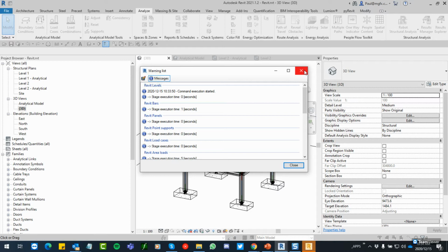So typically the sort of error that you might find, you perhaps know if your minimum CPU RAM is able to handle these programs simultaneously. No, I don't. I don't know what the minimum is, but minimum, that's a relative answer to me. If I can answer it differently, Marcus, just from a Revit modeling perspective, I can already tell you that depending on how large the building is, if you've got this computer here, for instance, on a sort of a medium-sized building, this computer couldn't handle it anymore after a week's worth of the guys putting up a file that's 600 megs and it would crash. So no, but you're welcome if you want to have a guideline.